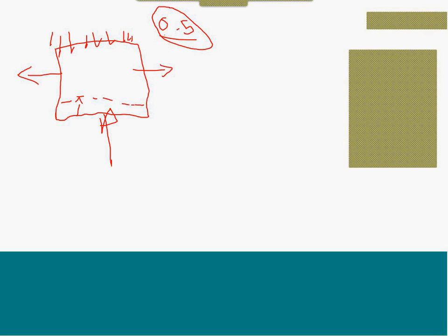If it is above 0.5, say 0.6 or something, it becomes an illogical situation. That is, if I am compressing this by 5 units, I am expanding this by 6 units. If we see the absolute ratios, then we should be able to understand why I am talking in this way. So for the first question, you can see yes, there can be volumetric changes. For the second question, this explains why we cannot go above 0.5.